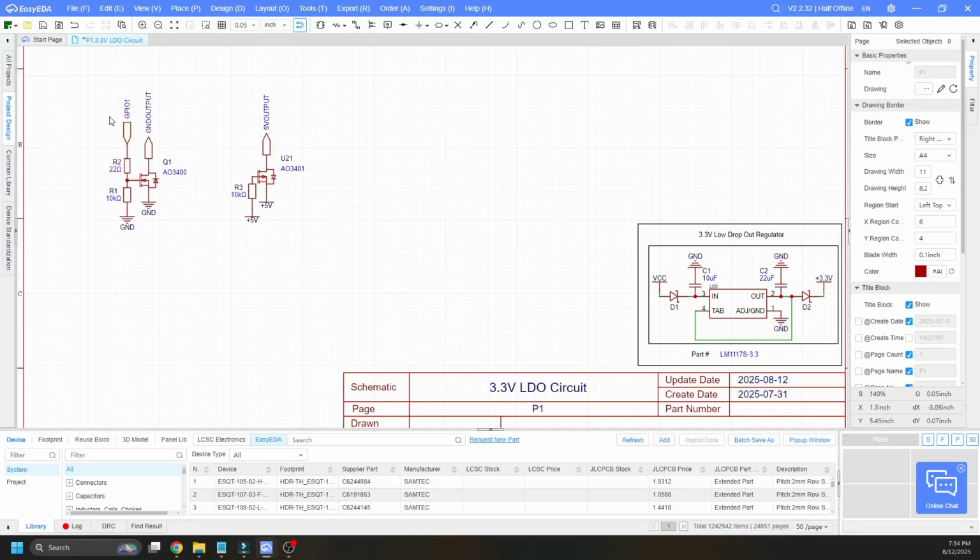So you could damage the microcontroller by backfeeding it. Now, it can seem a little counterintuitive because earlier we were talking about how these MOSFETs can handle up to 30 volts. Well, let me show you how to turn on a P-channel MOSFET with an N-channel MOSFET.